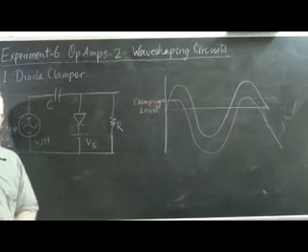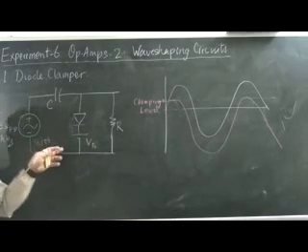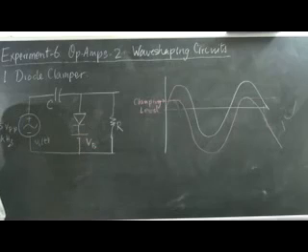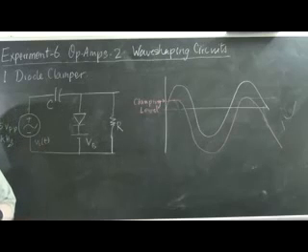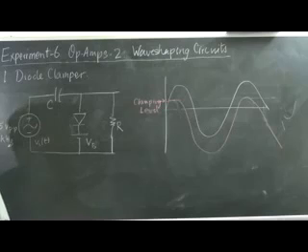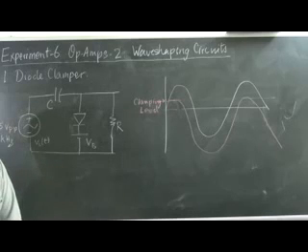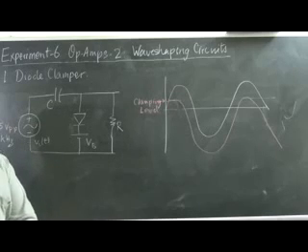The resistor of course remains and serves the same purpose that it did when the battery voltage was 0. So all you need to do is to exhibit the input and the output waveforms on the two channels of the oscilloscope, making sure that the output waveform at least is watched in DC mode so that the DC shift of the output is clearly seen with respect to the input.